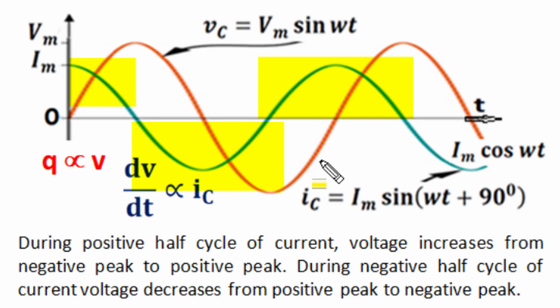voltage across the capacitor. This is also true as charge is proportional to voltage, and current becomes the time rate of charge flow, proportional to the time rate of voltage change. Positive current means positive change in voltage with respect to time, and as time increases voltage also increases for positive charging current, and for negative charging current dV by dt becomes negative. That means increase of time will result in decrease of voltage magnitude, as shown by this orange characteristic here.